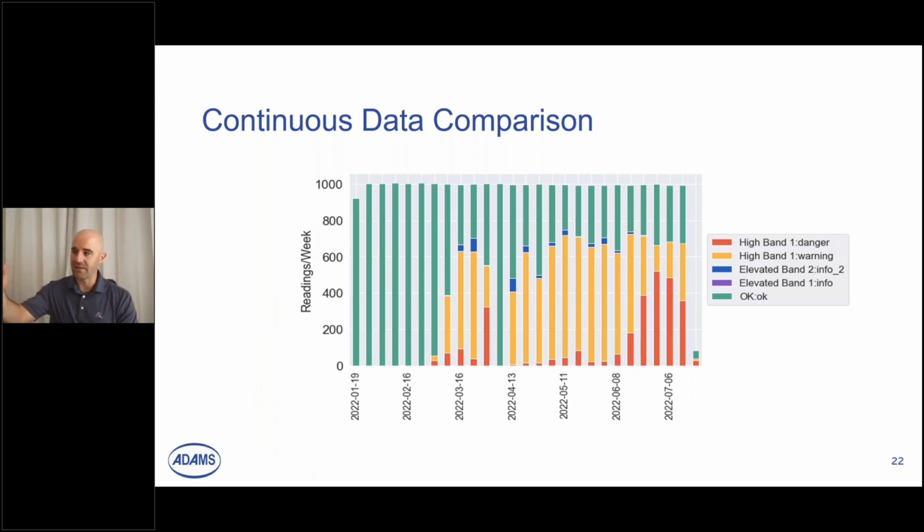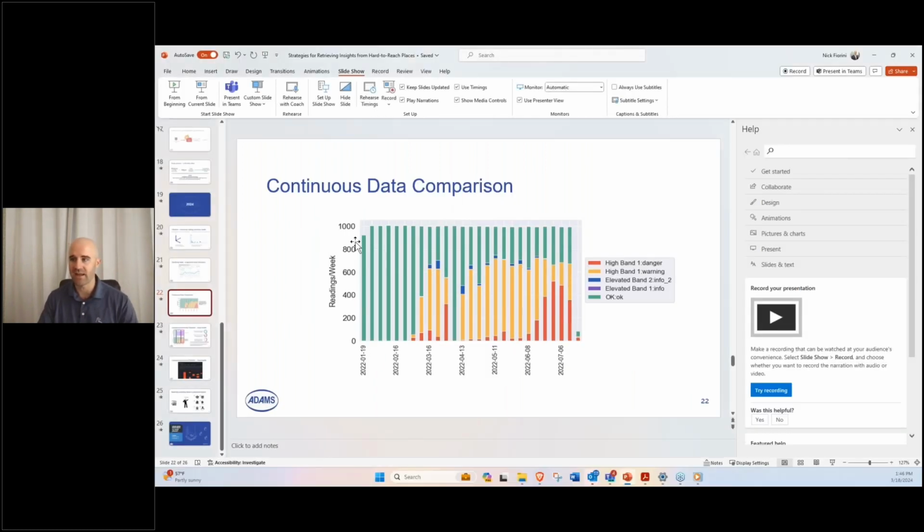And if you look ahead towards month 6 or 7, we're seeing the magnitude and frequency of these vibration readings occurring more often, happening at a higher frequency. So that is making the health score closer to 100, which is our worst score. So this is giving alerts now via text and email to maintenance to come take a look at me. So on the far right of the screen is 100% health score, far left would be 0. And that's how we identify anomalies and give them that score.